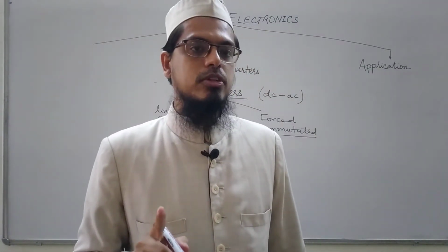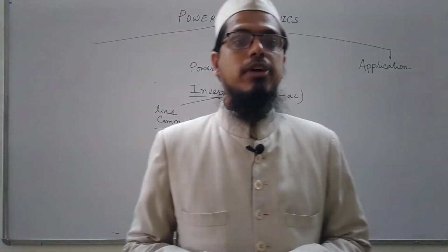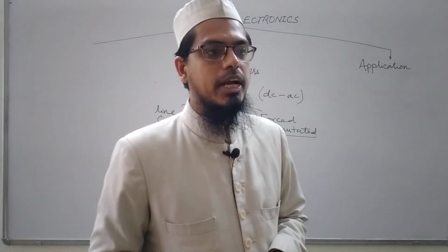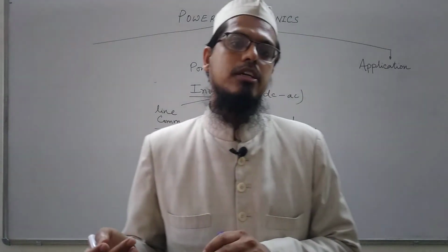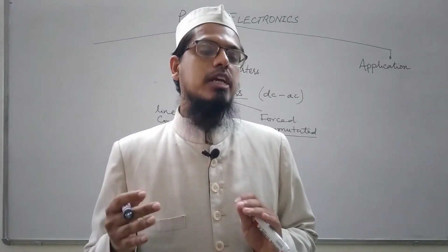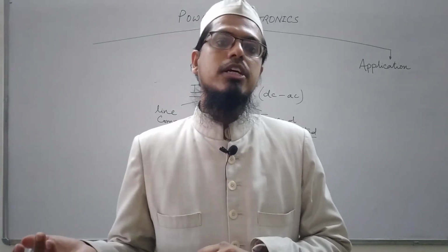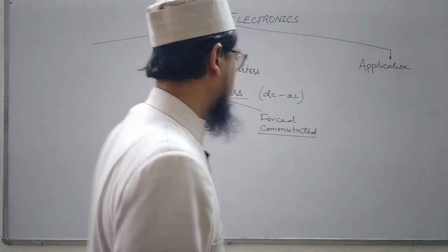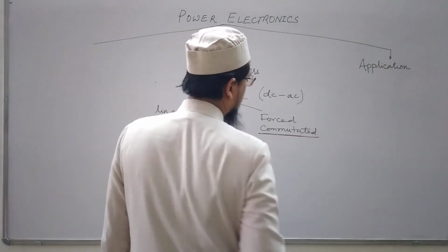Okay. So the circuit topology remains the same. The only difference is that the firing angle alpha is kept higher than 90 degrees, which ensures that the average power is transferred from the DC side to the AC side. There is a bidirectional power flow, but the average power is negative. That means the DC side is feeding the AC side. So basically that is a line commutated inverter.